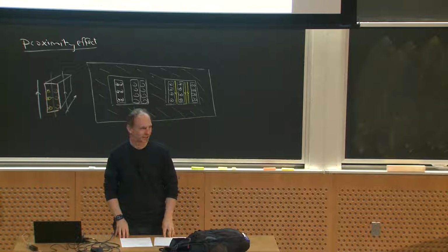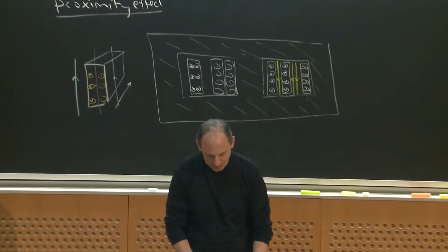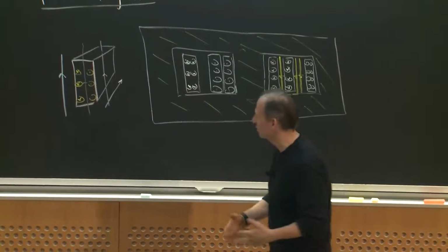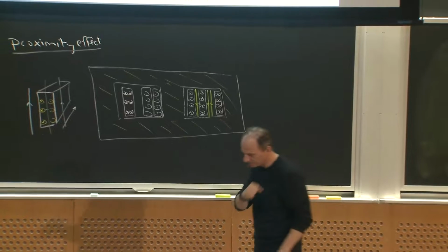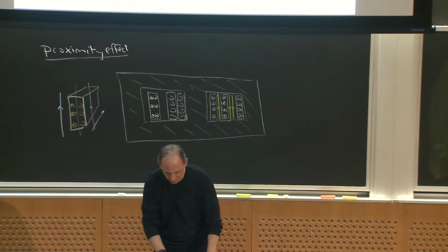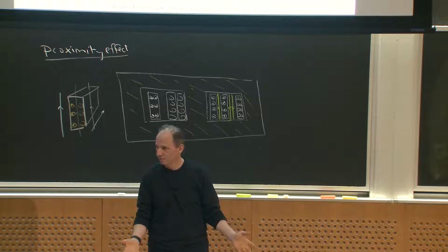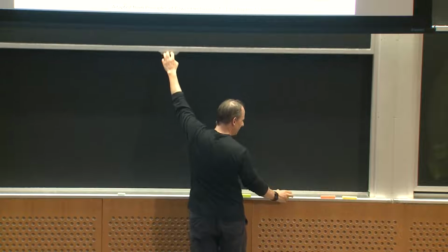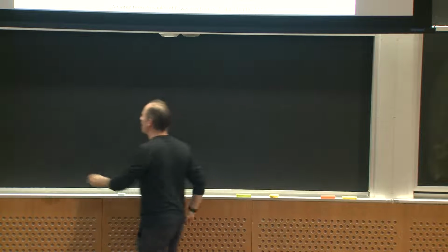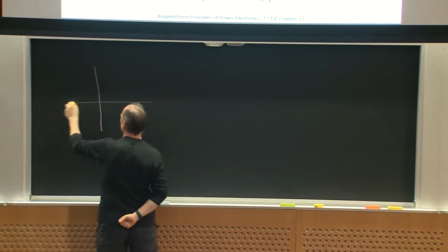And these are just some things to think about. Watch out for skin effect and really watch out for proximity effect if you're carrying high AC currents. The other piece, of course, of any inductor or any transformer is the core, okay? And ideally, a core material is lossless, right? We have always sort of idealized, if you will, our BH characteristic of our core to look something like this, right?